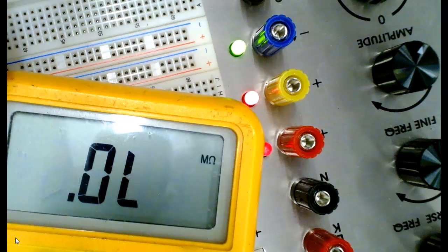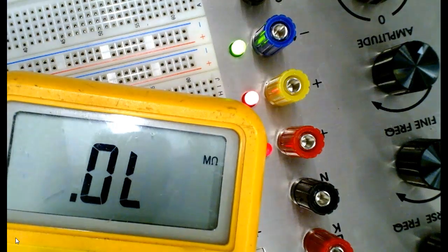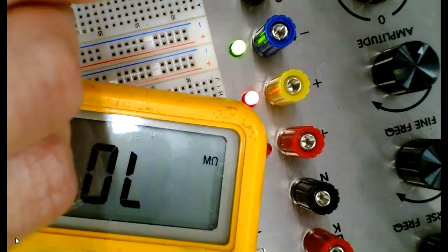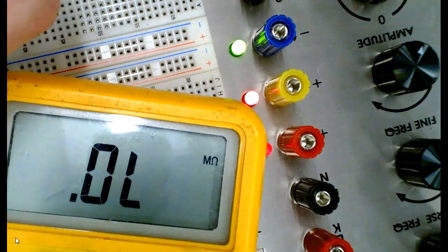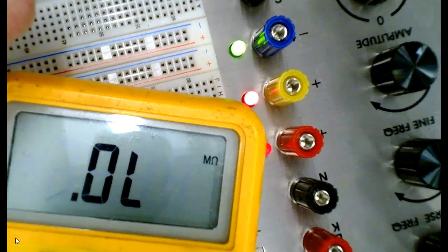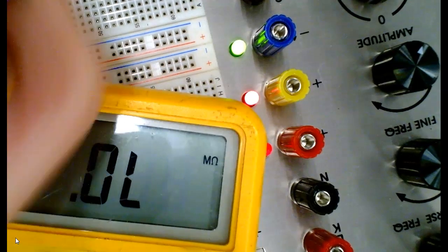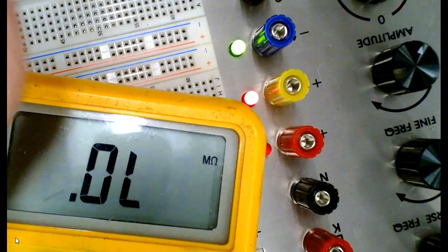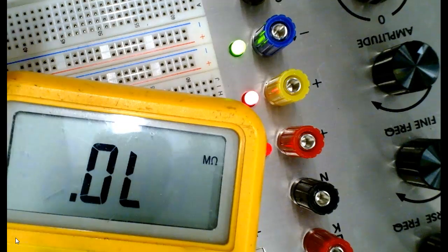Now, remember, this is the way we would check these diodes to see if they're good. So what we're trying to do is look at a real high ratio between this way. So this is infinity, right? Understand? Let me get my fingers off of it. This is the highest. We call this infinity, but there's really no such thing as infinity, right? It's just that it's got a resistance so high that I can't measure it.